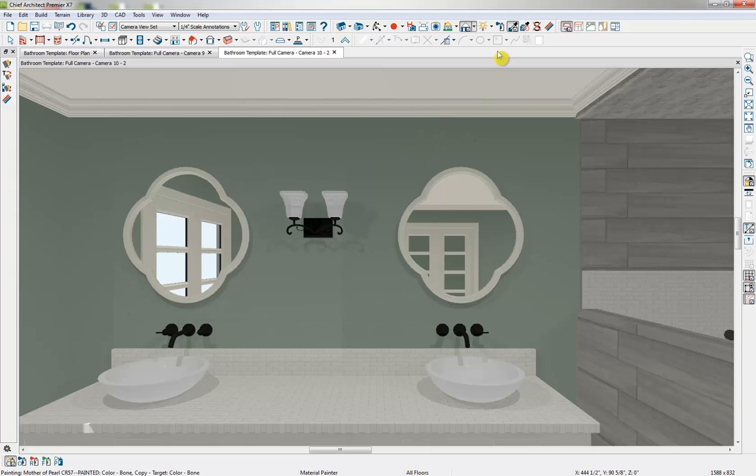And when we are copying and pasting materials, we have the ability to adjust our scope. So we can paste just a component, so that would be just the countertop, which we just did. We can paste it on through the whole object throughout the entire room, and then throughout the entire plan as well. But with the color, we also have this option to blend colors with materials. And what this does is it will actually blend that color with the existing texture. So we can easily apply colors within the space or within our library browser to a material that we want to maintain the texture of.